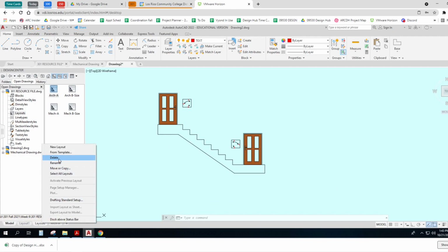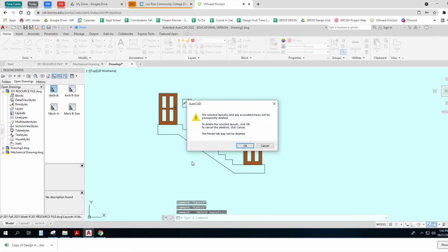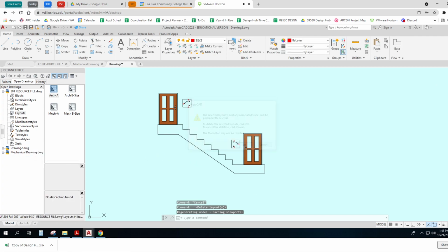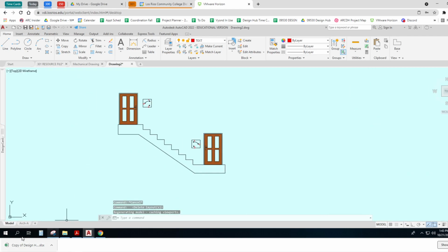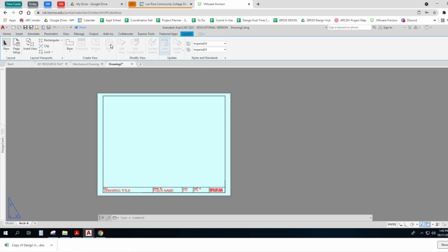And again, I like to delete extra layouts, just to keep from confusing some of the people that will be reading this. And I think I remember I need to go to my depth points layer, click my layout tab, and put a rectangular layout in.